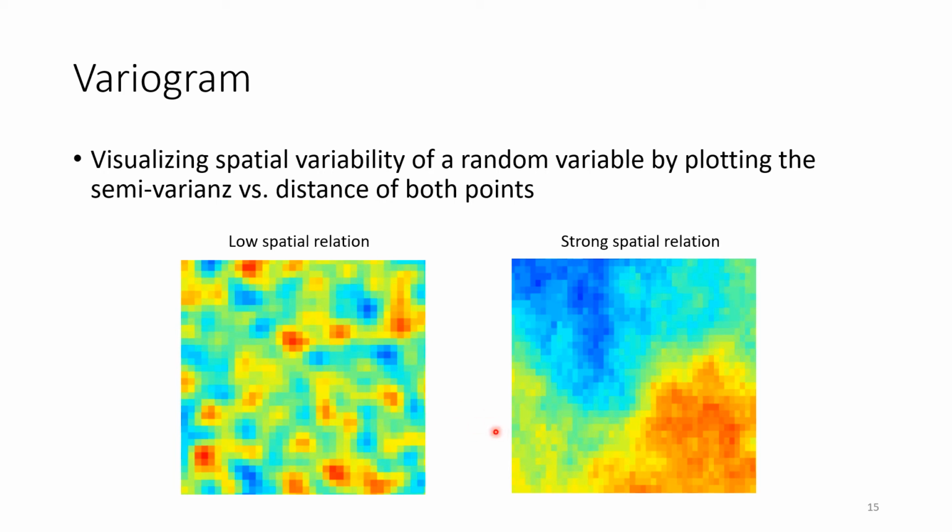So again, using hydraulic conductivity as an example, you can have small variations if your soil is very heterogeneous. You might have solid blocks of rock in between, which have low hydraulic conductivity or almost none. Then you can have very large contrasts on a very small scale, or if you have clay lenses or stuff like this, that could happen.